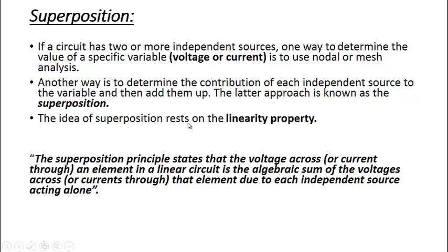The idea of superposition rests on the linearity property. That means the superposition principle is applicable only to linear circuits. If we have a non-linear circuit or a non-linear component, we cannot use it. For example, current and voltage are related to the resistance linearly because V is equal to IR. If we have to calculate the power by using the superposition principle, we cannot, because power is a nonlinear term. Power will be V square by R or I square R, which is a nonlinear term in terms of